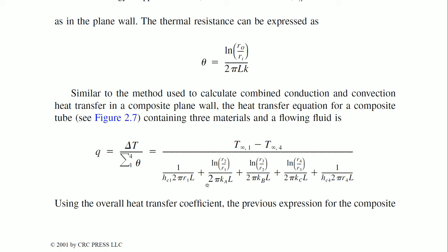In certain fabrication processes, the materials are compacted. Typically, the best example is forging. If something is forged, the conductivity will be high. And if something is made by some other, normal process, especially gravity die cast or gravity mold, there are always microscopic voids inside, and that will not have the same K, though it is aluminum.